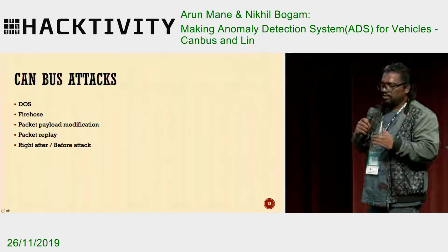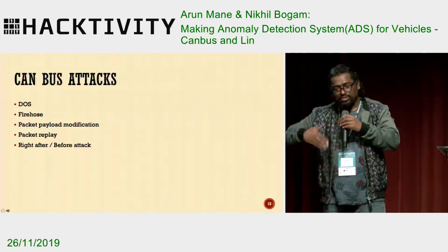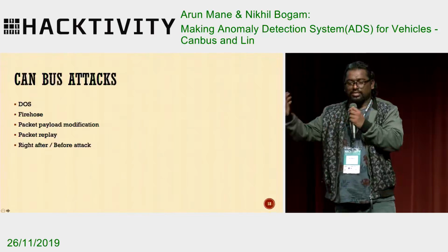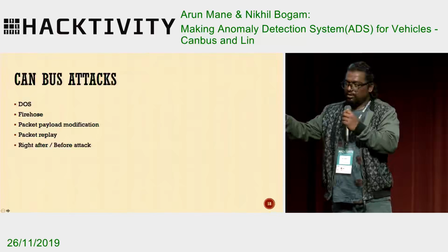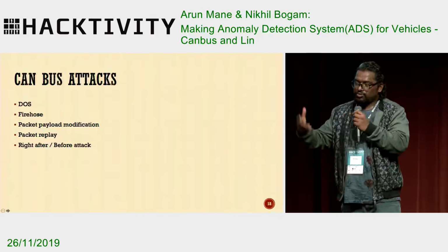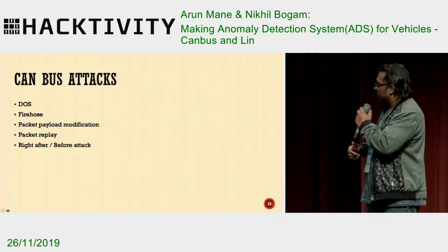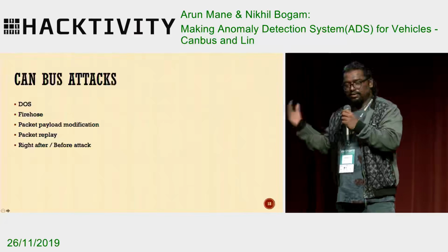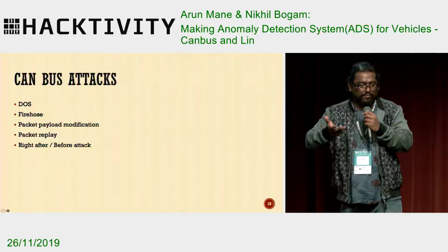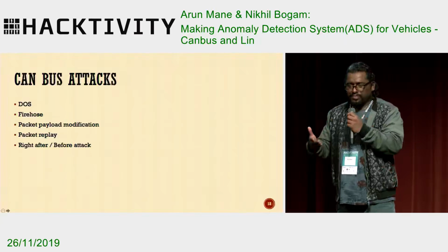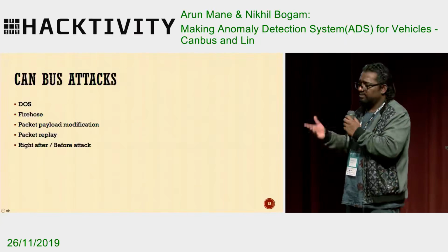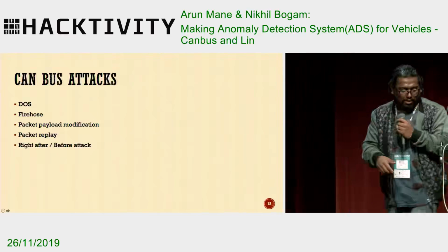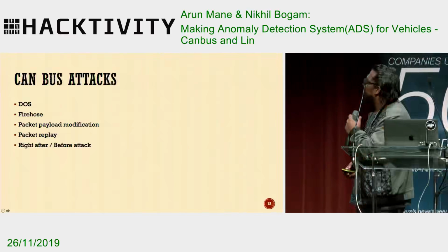Right after, right before: those are the kind of attacks where you send the valid message, and after that you send the malicious message, and you can see the difference in the attack or other response on the particular ECU or other ECUs in the car as well. And again, if you send the malicious message and after that you send the valid message, you can see the difference. Specifically, when we do testing of the gateways or other switches in the cars, these kinds of attacks you can do in testing those things.